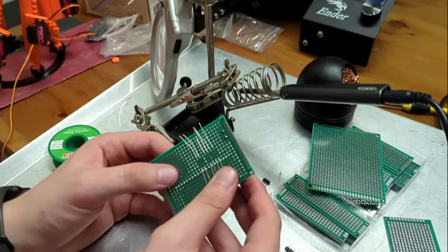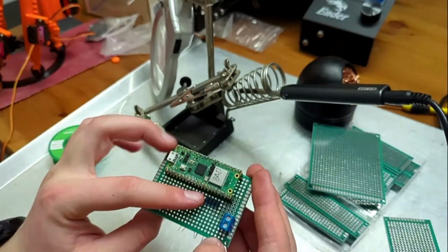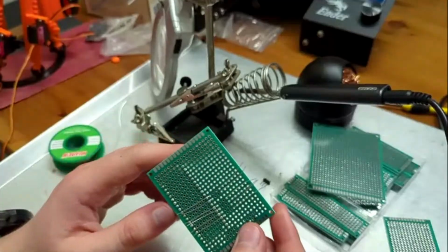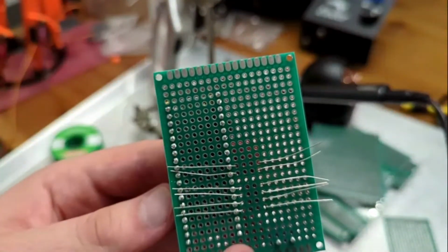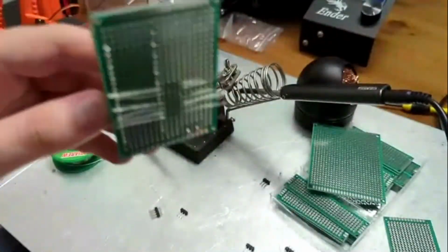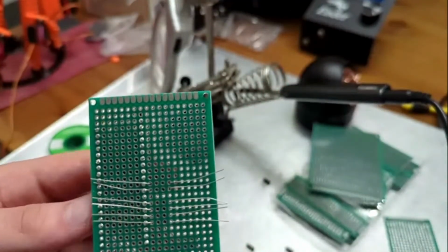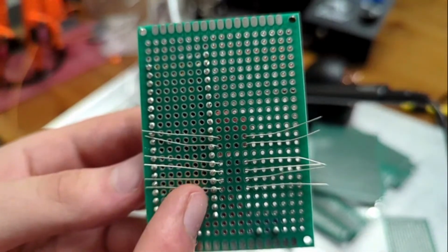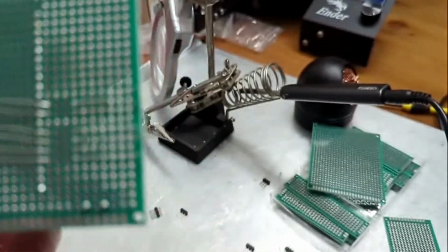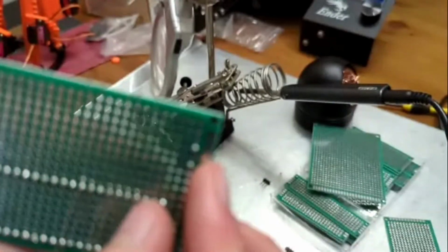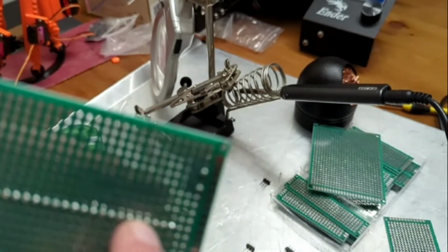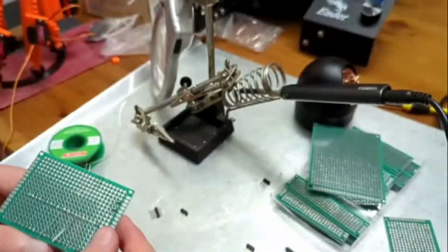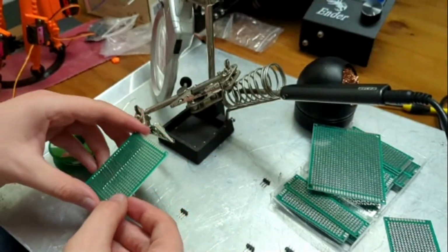Now, one tip I have for soldering resistors on this is you see I've got them all lined up in a row next to the pins I want to connect, and then on the back side, what I do is I bend out the leads so that it basically holds itself in place. So while I'm soldering, it's super easy to just put a little solder joint on each of these points, and then it's in there permanent, and I can cut off the rest of the lead. Additionally, these leads help as a nice little way of connecting to the actual Raspberry Pi pins without having to make a giant solder joint. So I'll just get these soldered up real quick.